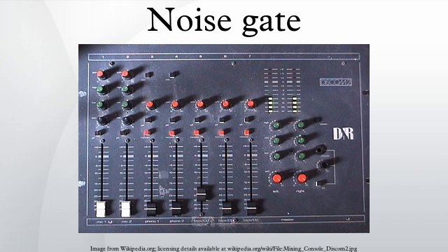This can usually be remedied by the inclusion of one or more overhead microphones, which can act as a general audio glue for all the other gated sources. Noise gates are useful when editing live recordings in order to remove background noise between passages or pieces of dialogue. However, care must be taken in setting the gates so they do not trigger due to spurious noise, such as when people move chairs. For vocal applications on stage, an optical microphone switch may be used. An infrared sensor senses if somebody is in front of the microphone and switches on the microphone.